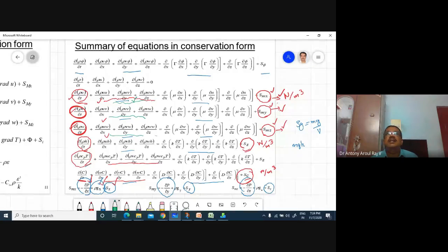This acceleration is not temporal acceleration. It is convective acceleration. Convective acceleration is like a flow happening in a nozzle or in a converging space or constriction. Nozzle means don't always think about a funnel shaped nozzle. This nozzle effect can be created by a converging building structure or converging tree structure or whatever the structure may be. When the flow is happening from a bigger cross section to a smaller cross section, acceleration will be taking place. At that point only these three terms will appear, if there is convective acceleration.